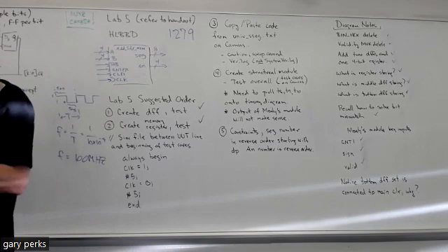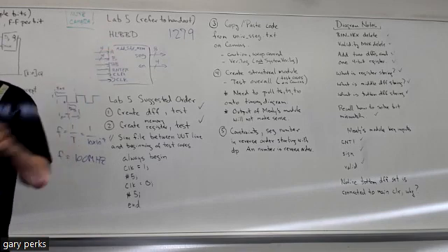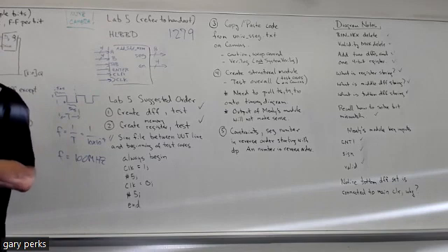If your validity wasn't 1, if it was 0, the display would just show all dashes. So that's why you see set connected to the main clear. Because we want the output of that validity check flip-flop to go to 1 when we reset, so the zeros will be shown.